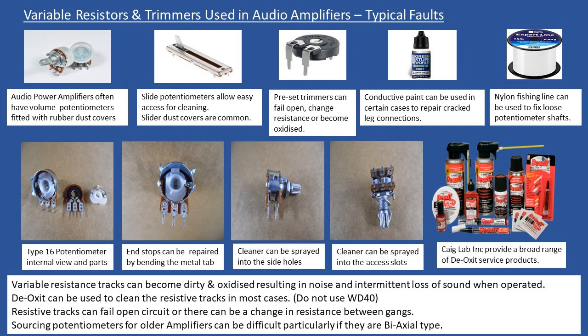I can spray directly into there and then again work it backwards and forwards. Now when you're doing fault finding, because this is a variable resistor, it's a simple case of using your multimeter on resistance. From the ohmic value, 20k, you will have a nominal 20,000 ohms if I measure from the two outer points, not with reference to the wiper for the potentiometer.